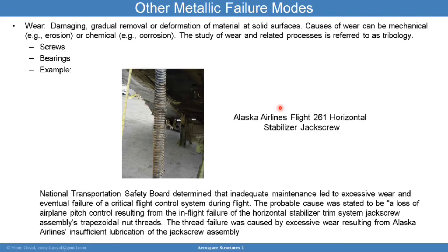And the thread failure was really caused by the excessive wear resulting from Alaska Airlines' insufficient lubrication of the jack screw assembly. So that insufficient lubrication led to that accelerated wear that then was the very root cause of the issue that was seen, which is the loss of airplane pitch control from the in-flight failure of the horizontal stabilizer trim system.